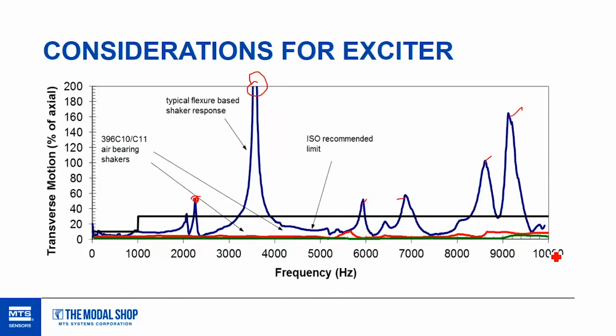So at certain points, you'll have these modes of vibration where you have a lot of X and Y motion for a given Z motion. And as a percentage, if you think about that, 100% here means that if you're running, say, a 10G acceleration sweep, at 3,500 hertz, you're actually going to have 10 Gs of lateral motion.